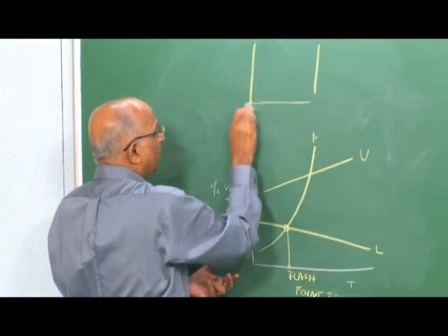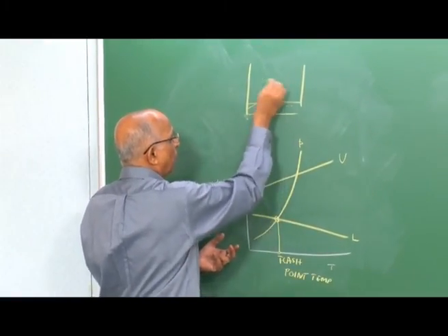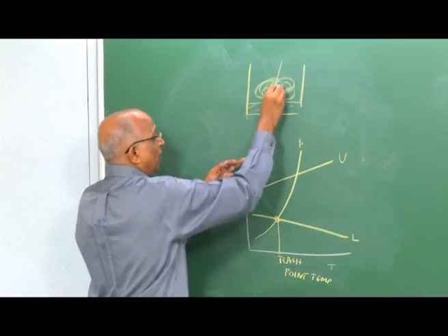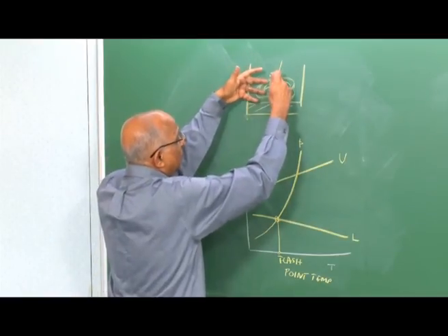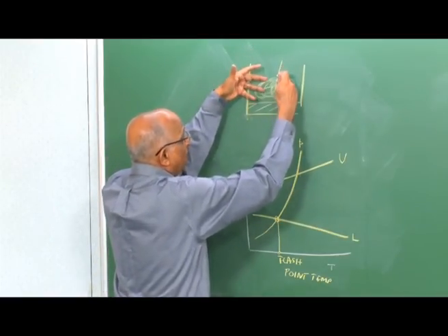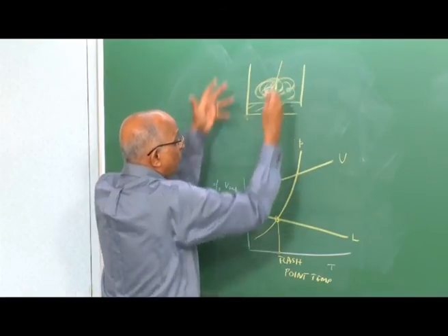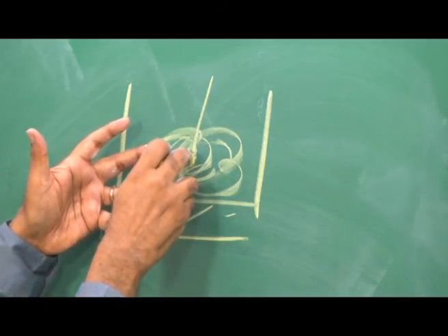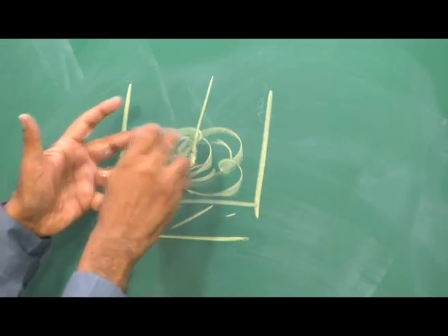I have maybe kerosene or petrol over here. I form a mixture over here which is, let's say, at the lean limit, and supposing I put a matchstick over here, it immediately burns and the mixture is finished. It just flashes into vapor and then the vapor gets consumed, and that is why it is known as flash point. That means the amount of vapor is still not sufficient to continually keep the fire on.